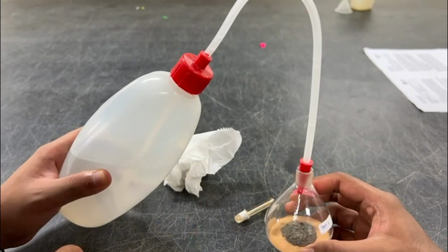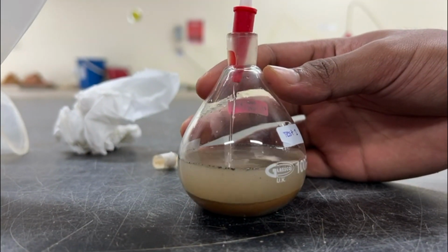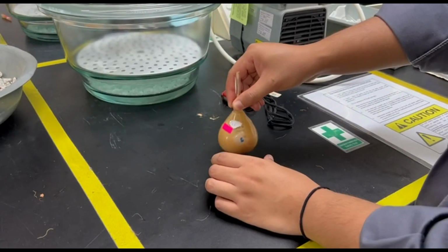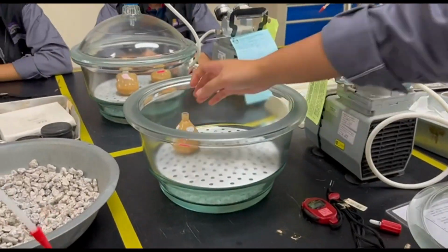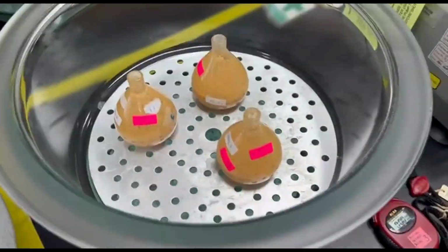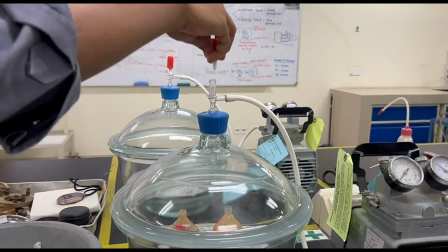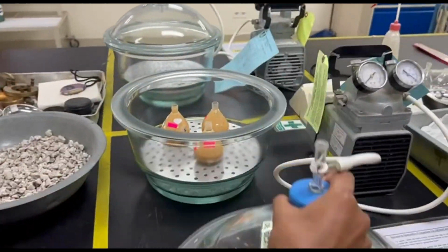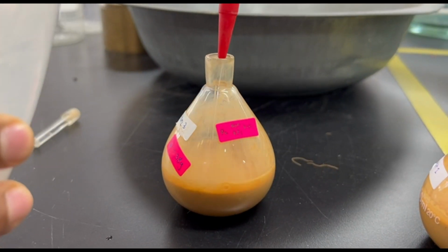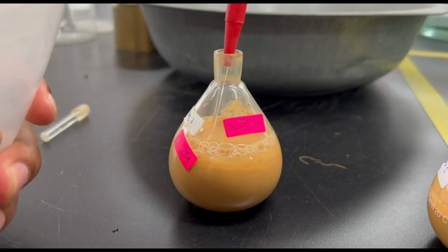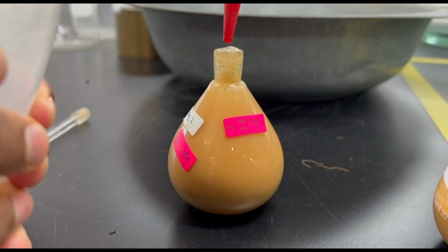Distilled water was poured to make the density bottle half full and then were mixed together. Entrapped air was removed by applying partial vacuum for 10 minutes. After removing the density bottle from the vacuum, more distilled water was poured into the bottle and completely filled without any entrapped air bubble. The stopper was then placed on the bottle.